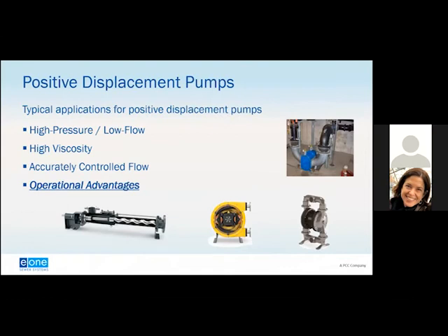So typically in the wastewater world, we don't see a lot of positive displacement pumps. Usually, if you're familiar with positive displacement pumps on the wastewater or even on the water side of the industry, it's in an application where it might be a sludge or a polymer, or something that is a little bit thicker than water. So where you would typically see the application of a positive displacement pump is areas where you might have high pressure, low flow. They're usually more effective in operating against high pressure and low flow applications.